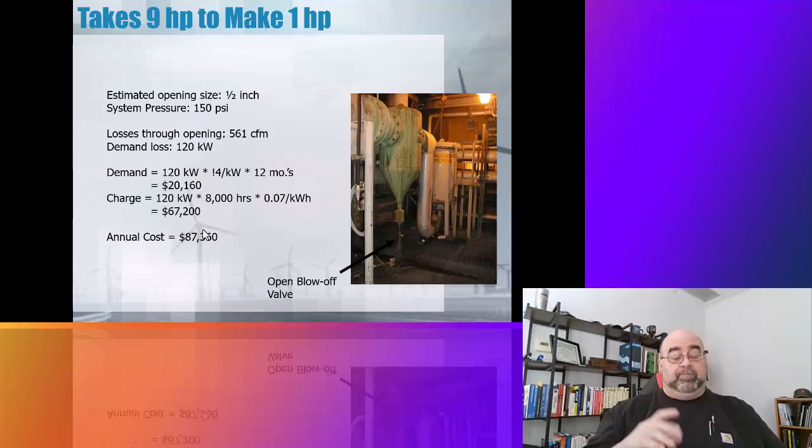Long lengths of flexible air hose. Now, what people don't realize is you get pressure drops across an air hose. You've got air leaking out of the surfaces of the air hose, not just where you make the connections and so on. There were a number of issues identified within the compressed air system at the starch and gluten packaging plant. These included an air pressure drop from 110 to 45 psi from the compressors to the end of the packaging line.